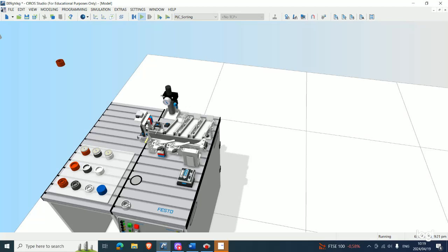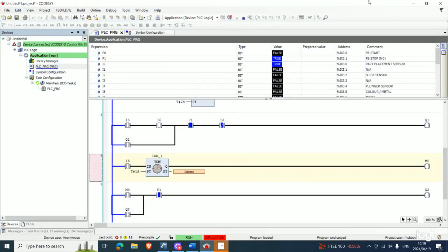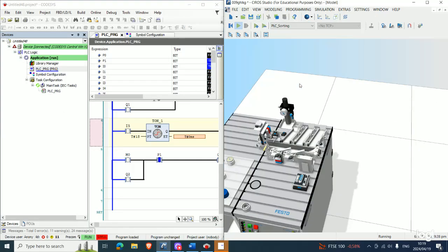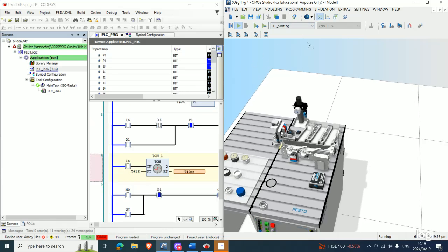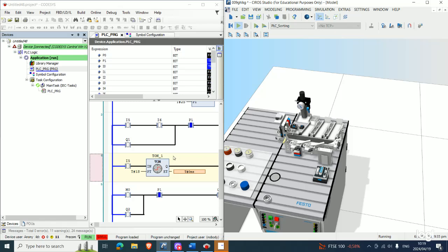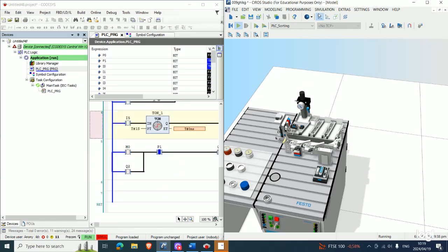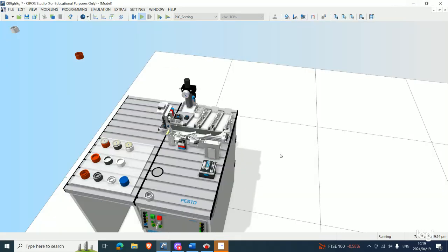The metal part would be a perfect candidate for this. I want you to see both screens on what's going to happen to I5. So now the metal part is on, and then we press play. Now you can see both of the diverters are getting activated, and that is not supposed to happen, right? For a certain part, we only want one diverter to be activated.